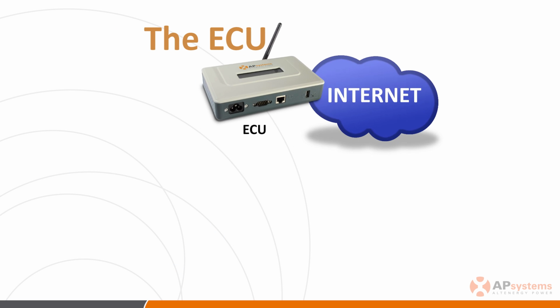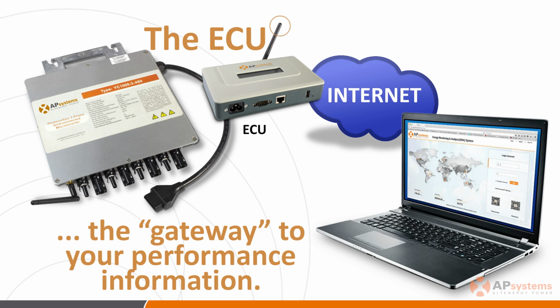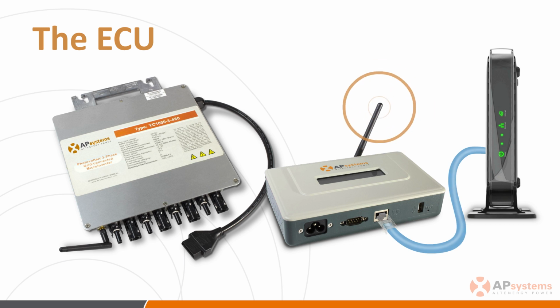The ECU, while optional, is an essential component of the remote monitoring system that should be thought of as the gateway to the performance information that can be retrieved from each inverter and its assigned PV modules. Again, the ECU uses the Zigbee protocol to communicate with each of the inverters. Please note that the ECU is not a standalone wireless device and requires an electronic bridge or direct Cat5 connection to communicate to a network router.